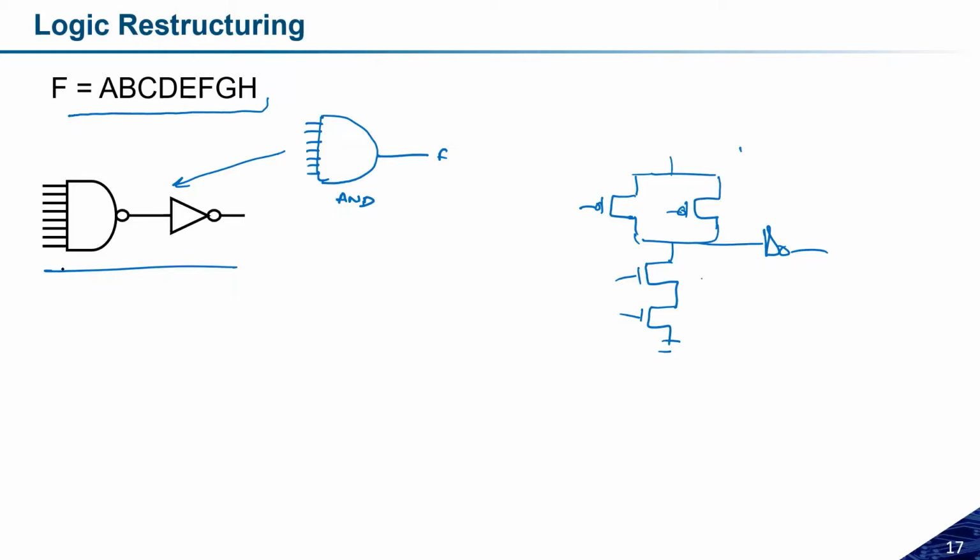Got it, sir. Because in a CMOS-based structure, we can simply design the inverting kind of things. We can design the NOR gate, the NAND gate, the inverter, but we cannot design an OR gate or AND gate. So for that purpose, I need to use an inverter just after the NAND one, and this is the reason why I have made the design like this.